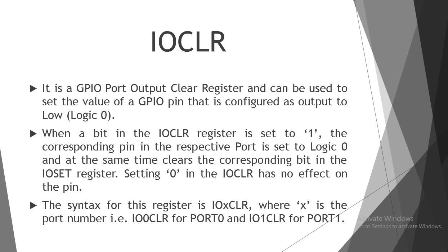The syntax for this register is IOXCLR, where X is the port number. If we want to use port 0, then we have to write IO0CLR, and if we want to use port 1, then we have to write IO1CLR.